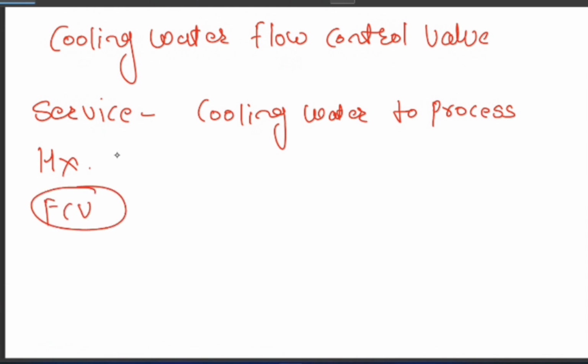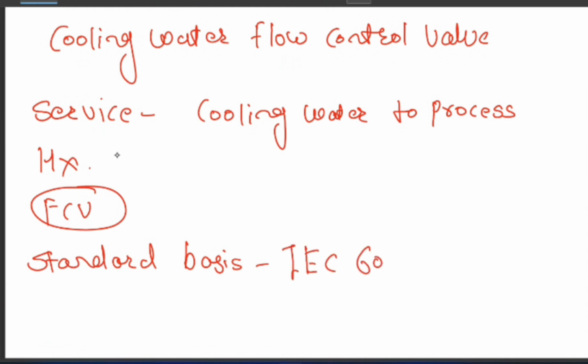Flow control valve. And you should know the standard: what standard the control valve has to follow. As a process design engineer, you should know the codes and standards for everything. Whatever you are going to design, there are certain standards given. So it is IEC 60534, for liquid.